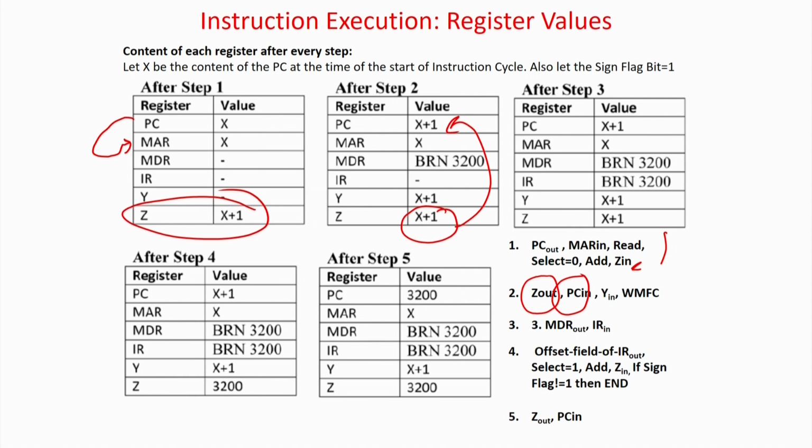And as I told you, as a special case, in case of jump addresses, the updated value of PC is also given to Y. We have already seen Y, because you have to add the updated value of PC to the offset. So, you require 2 operands. One operand we are storing in the temporary register Y. Then you have to wait for some amount of time.